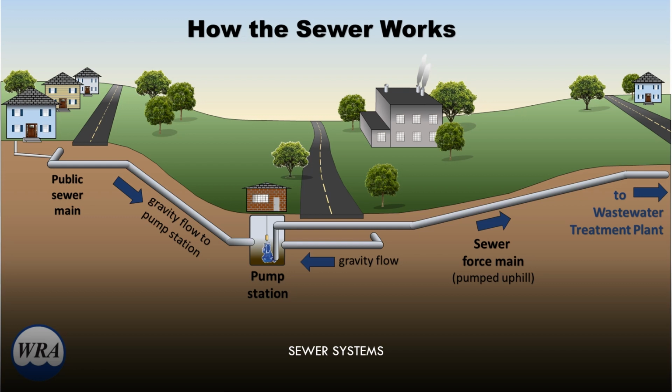Wastewater contains a lot of solids, which can make it hard to pump. Not to mention you can create deadly gases like hydrogen sulfide when you pump waste. But sewer mains in large areas are usually 3 to 5 feet in diameter, and sewer mains will flow into larger and larger pipes until eventually they reach a wastewater treatment plant. Now, usually wastewater treatment plants are in low-lying areas, which makes the engineer's job designing them much easier.